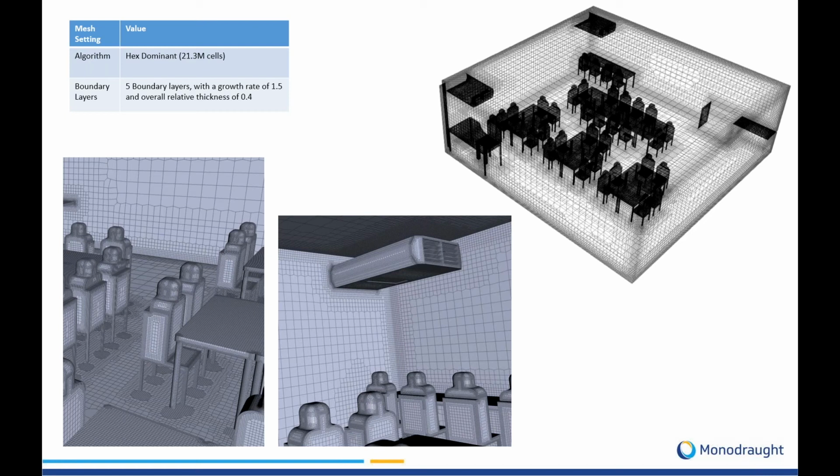So when we were actually designing the inside of the unit and we were trying to optimize the acoustic and the aerodynamic architecture on the inside, small elements we were able to do in 3 or 4 hours. However, larger ones, so the ones that we've got in front of you now, with 21.3 million cells, probably slightly longer. I think this one was about 15 to 16 hours.